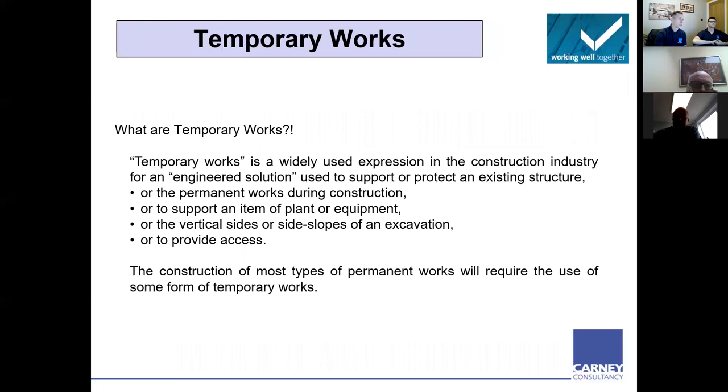So what are temporary works? So basically temporary works, widely used expression throughout the construction industry, but it's for an engineered solution used to support, protect an existing structure, support or protect the permanent works during construction, support an item of plant or equipment, the vertical sides or side slopes of excavation, or provide access. Ultimately, anything that will require a permanent work structure will need some form of temporary works.